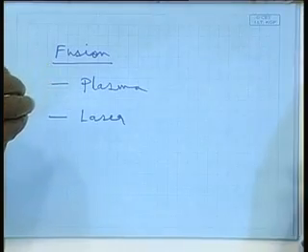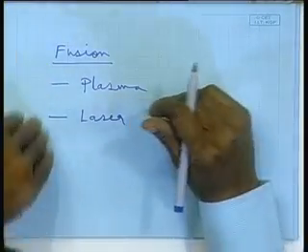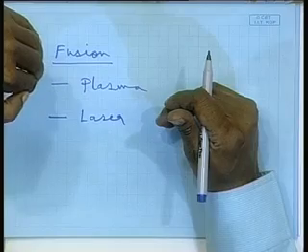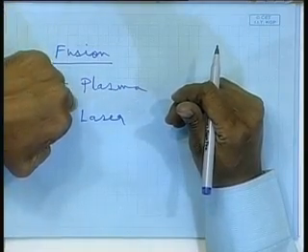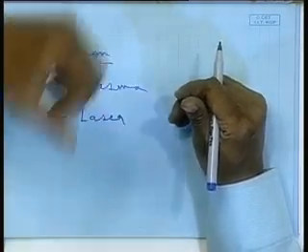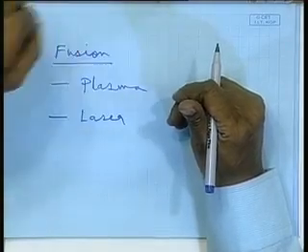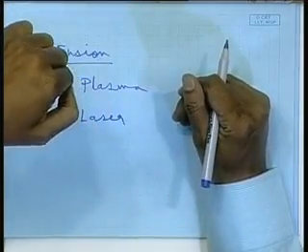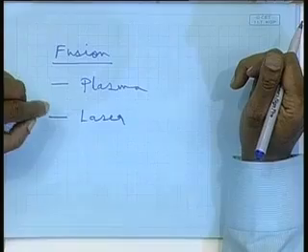So, what happens is, you can attain the required temperature immediately, and that plasma jet or the laser beam will have enough force to throw up the molten metal. So, the metal gets melted and it keeps moving. So, if I can momentarily generate say 3000 degrees centigrade, aluminum will be immediately cut. I am not allowing the heat to remain in position for a long time, such that heat gets conducted and the adjacent plate gets melted, right. So, that is how aluminum can be cut either by a plasma source or a laser source.